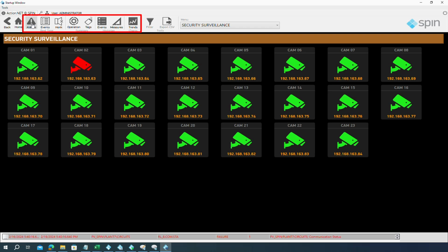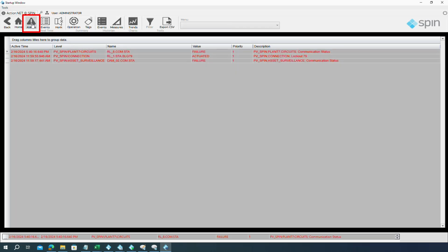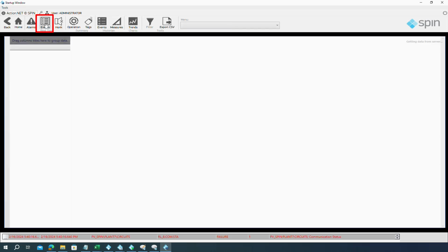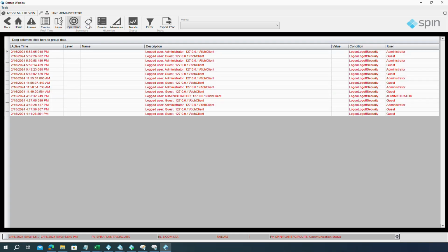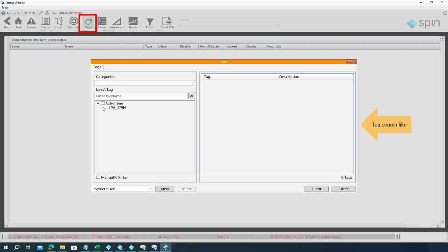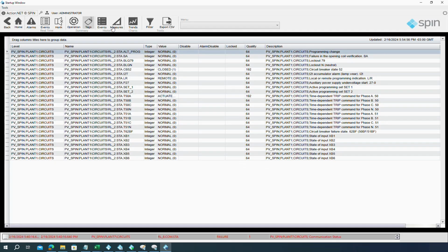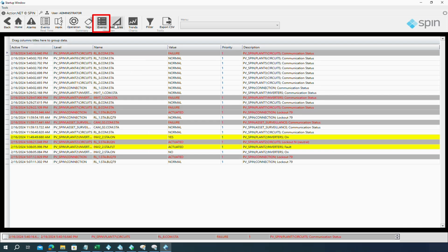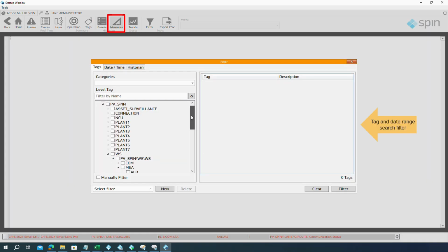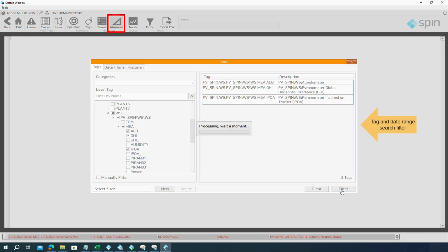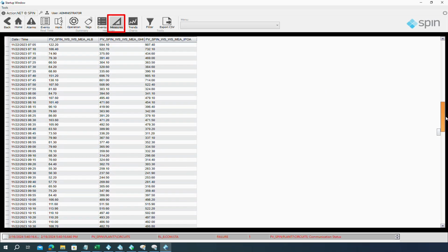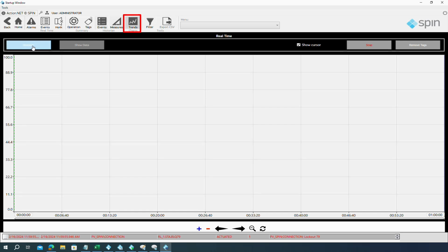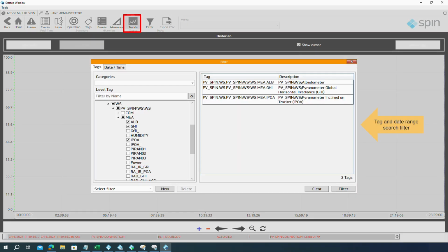Beyond these screens, there are the default screens of the ActionNET, such as the real-time online alarms and the real-time online events. Operation Summary, which displays user actions. Tags Summary, which uses the filter to define the tags to be searched. Event Summary Historian. Measures Historian, which uses the filter to define metrics and the period to be searched. Trends, which displays tabular measures in an interactive trend chart.